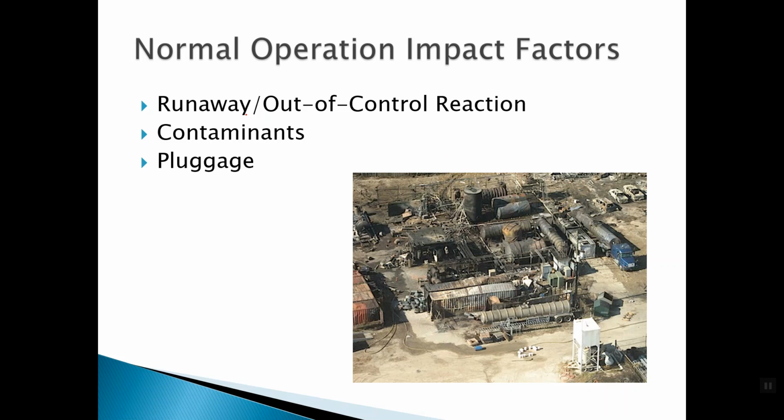So if we have a reaction that gives off heat and it also goes faster as it heats up, that can be an out of control reaction. If we can't pull the heat out, we heat it up, it reacts, it's exothermic, which means it creates heat, which means it's going to get hotter, which means it's going to happen faster, which means it's going to create more heat. If you see how that is, that's a runaway, out of control reaction.